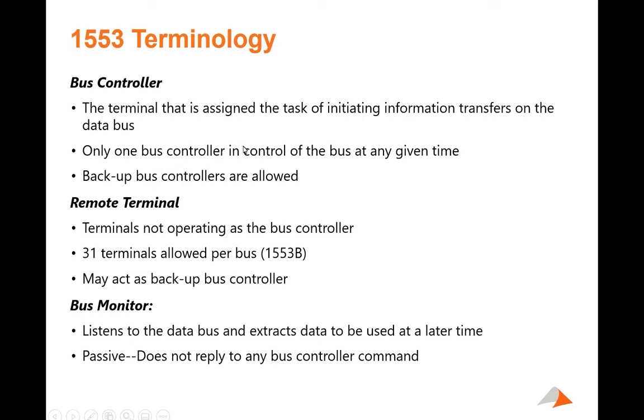One of the bus controller, so you have one bus controller at a time. You can set up backup bus controllers. There are different ways to enable them. The Air Force said under Notice 2 that you would not have a software-controlled backup bus controller, but a lot of people will implement a secondary line. It could be as easy as a discrete that gets dropped out that kicks in the new bus controller. A lot of people will have a serial line going between the bus controller and the backup bus controller, and just pass a simple message.